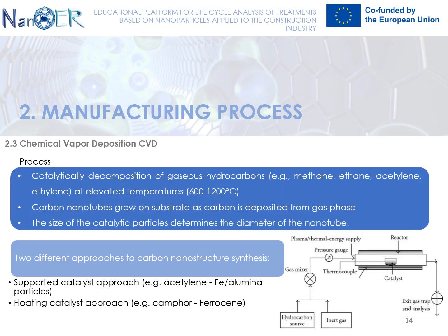Chemical vapor deposition is actually a thermal reaction of dehydrogenation. It is defined as the deposition of a solid on a heated surface from a chemical reaction in the vapor phase. The reactor comprises a quartz tube extended through a furnace. A transition metal such as iron, nickel, or cobalt is used as a catalyst to lower the temperature required, so the hydrocarbons in the gaseous phase are cracked into carbon and hydrogen.